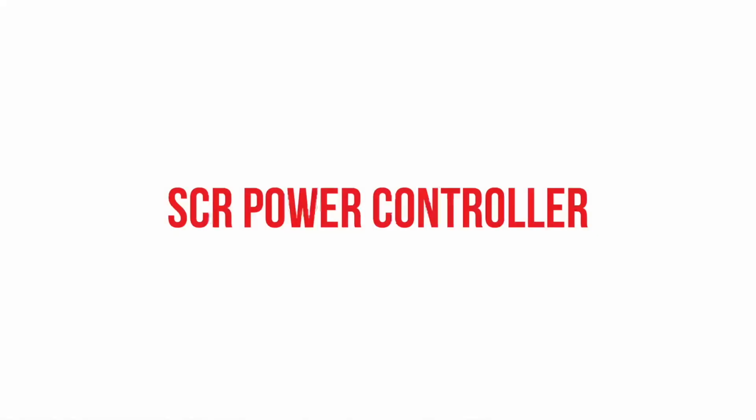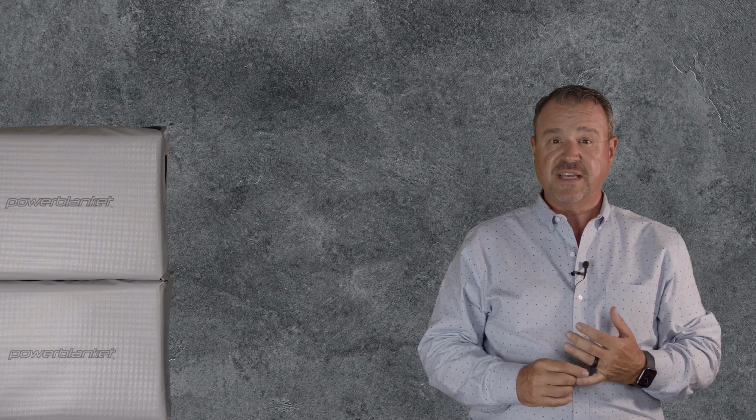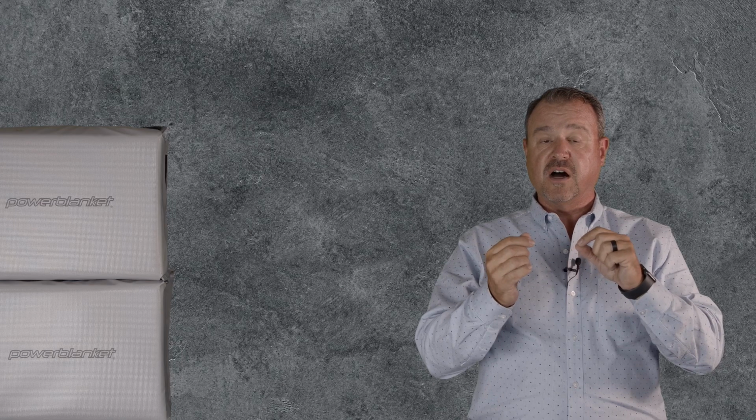An SCR power controller is another form of relay that you can use to transfer power to your heater in your process after a signal is given to a relay. An SCR power controller utilizes diodes that can turn off and on 120 times per second. Every single cycle crosses zero from AC to DC. There's 60 of those in 1 second. An SCR power controller is capable of turning off and on 120 times per second.